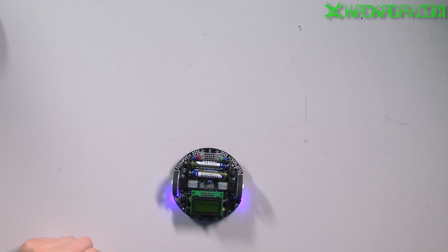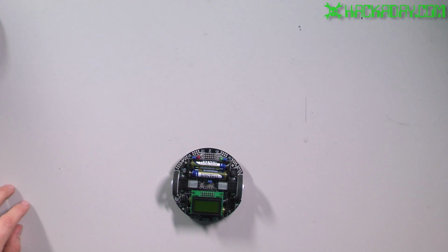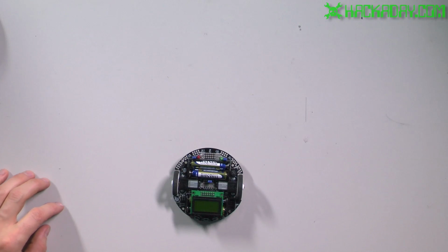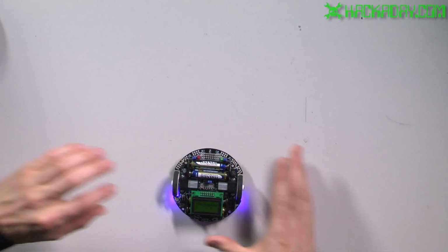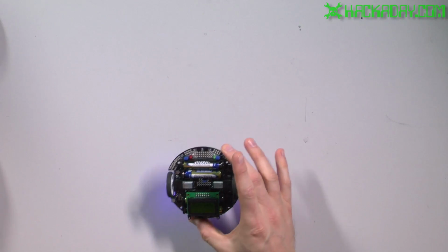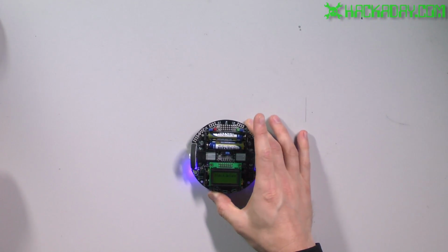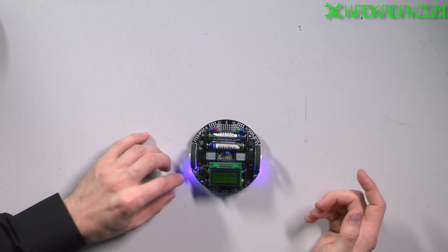So as you can see, it's a pretty peppy little robot, and that wasn't nearly as fast as it can drive. As you might have heard, actually I'll do it again here. You can probably hear the whining. I'll bring it up by my microphone real quick. You can hear that whining. That's because of the lock antiphase pulse width modulation.